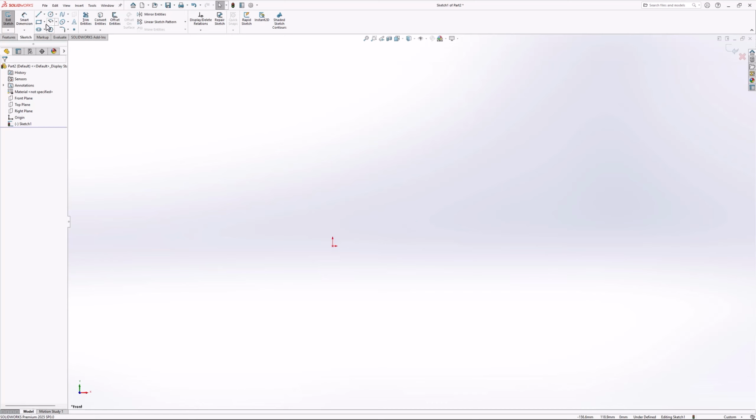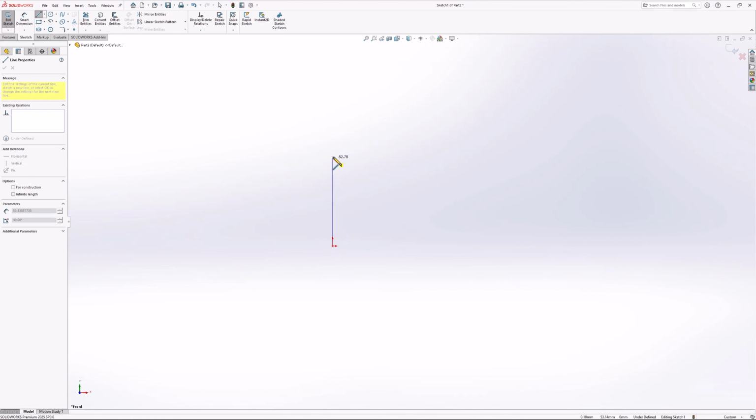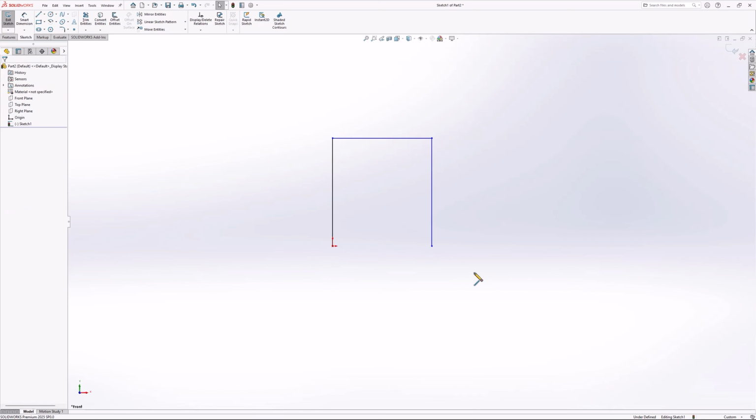If I wanted to create a channel profile, for example, I could click-click for the first two lines, and then click-drag for the third. This removes the need for me to hit escape after the final line, as the click-drag self-terminates. Give both methods a try, and get comfortable with using them.